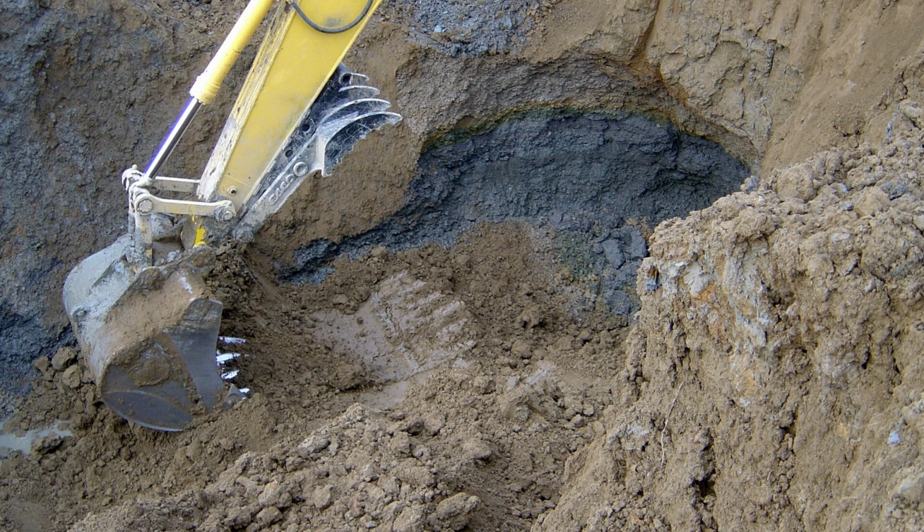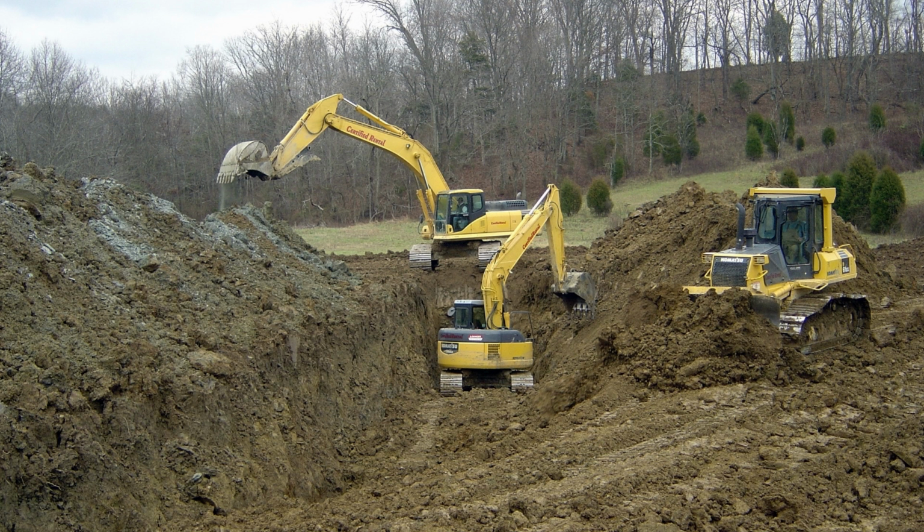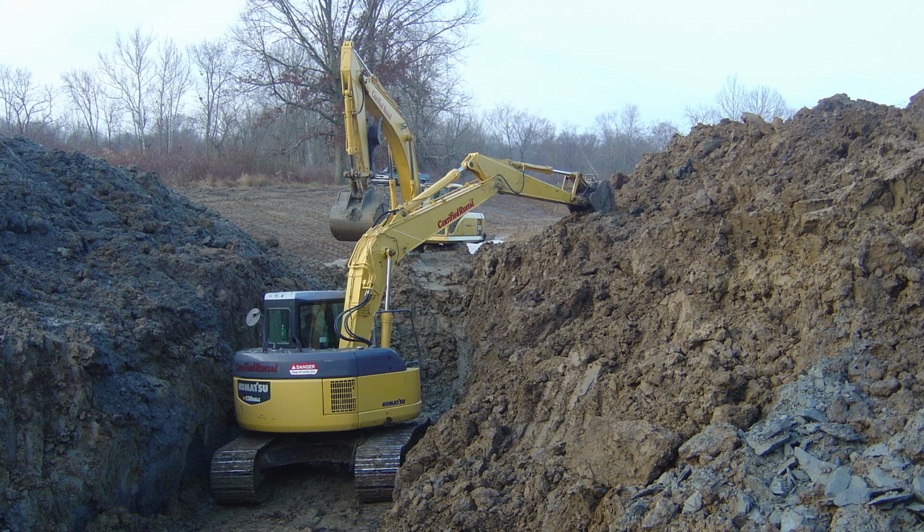The bucketed excavator is being used to compact the silt clay soil in the very bottom of the core trench. The excavator is reaching down into the ground 25 feet in this photo. A smaller 100 series excavator was used to help fill the bottom of the core trench. To avoid cave-ins of gravel, the operator of the small excavator would reach up and pull down the top portion of the core trench that was silt clay soil.